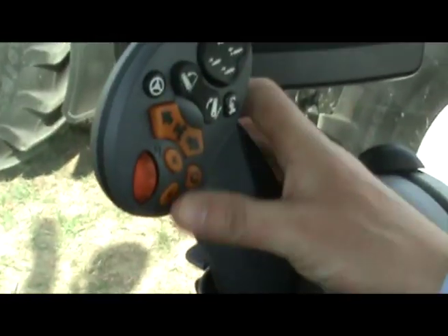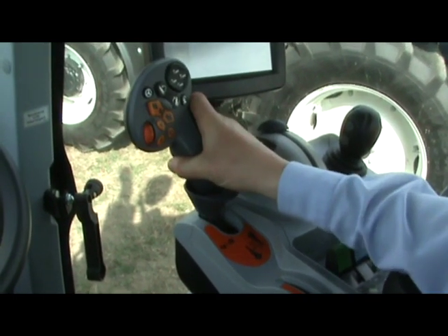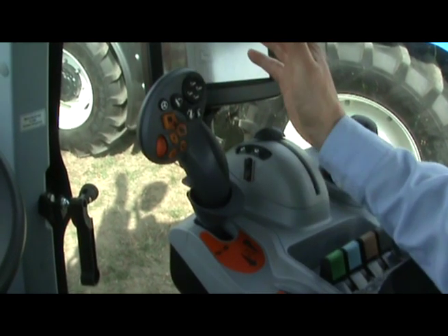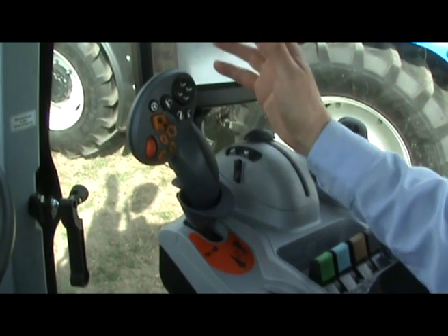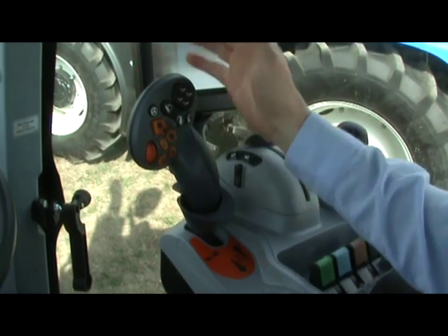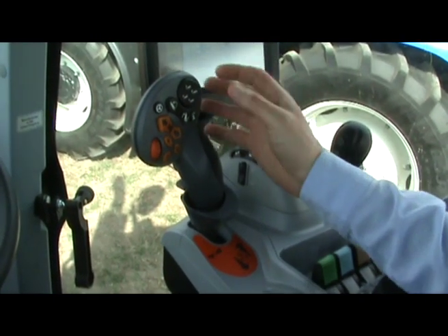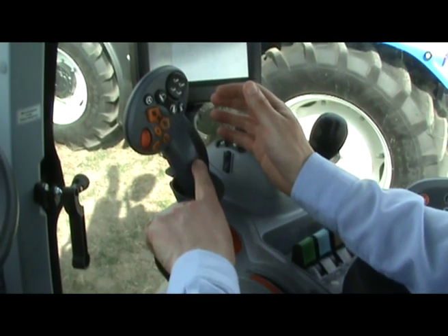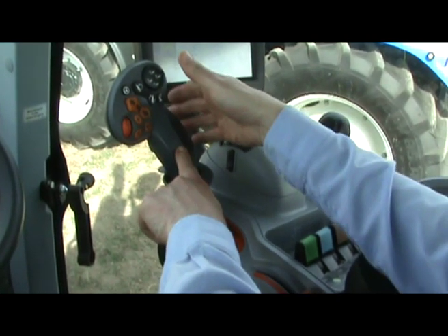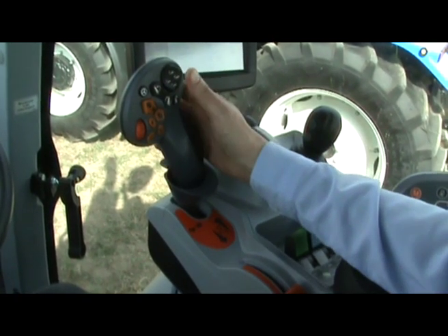CVTs on the auto command is a force-based control logic. So with this lever, you input a speed increase, you get to the speed you want to be travelling at, and you release the lever and it stays at the speed. The benefit of that is you get very, very fine control over the speed, but also this lever always returns to the most ergonomic place. If it was like some tractors on the market, you get to a speed and the lever stays at speed, which means the controls are at a funny angle the faster the tractor's going. With the system we use, it always returns to the most ergonomic place.